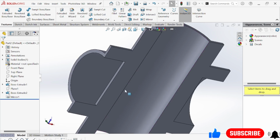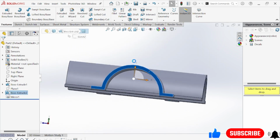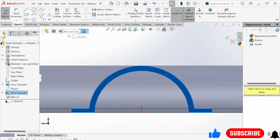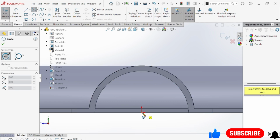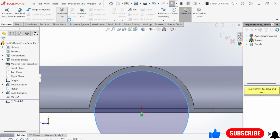Now here you see this is some external part. We need to trim this thing out. Go to sketch, select this part and make this one a sketch. Okay, now come here, make a circle with the help of center or origin point. Make a circle like this. Make this one okay. Go to feature, go to extruded cut.